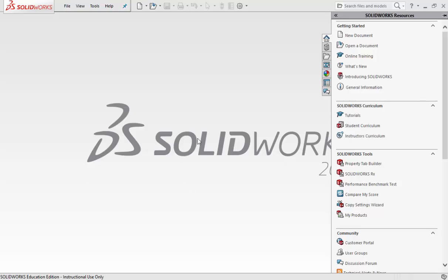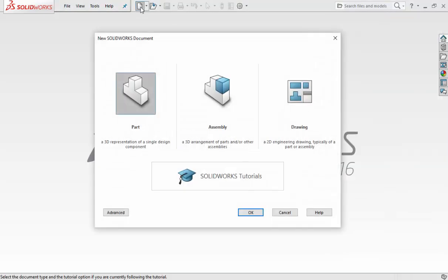We're going to get into assemblies. We've got 3 different objects that we're going to assemble together or put together. So you go to New, and this is a little bit different. We got to click on the assembly file. I don't know if we've done that yet. We've done parts, we've done drawings, we haven't done assemblies. So double click on that.